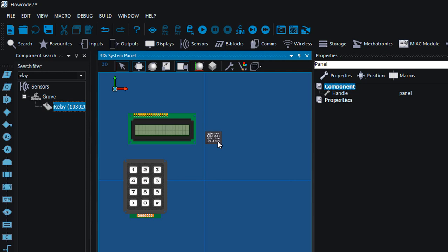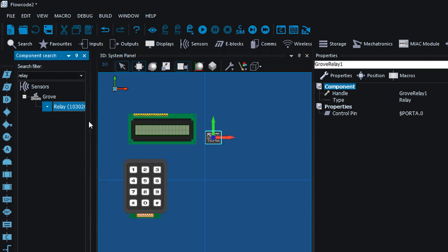A relay is basically a controlled digital device capable of switching much higher voltages and current than the normal microcontroller output pins. The output pin of a PIC microcontroller generally limits you to about 25 milliamps. If you want to switch higher voltages and current, such as to control a heater or a fan, like in this example, then we're gonna need a relay. We're gonna need a second relay.